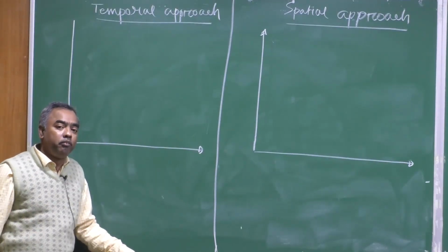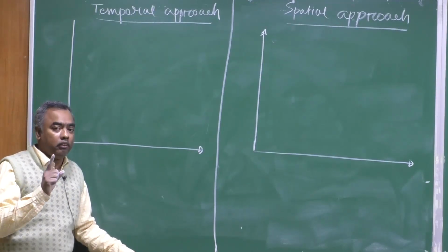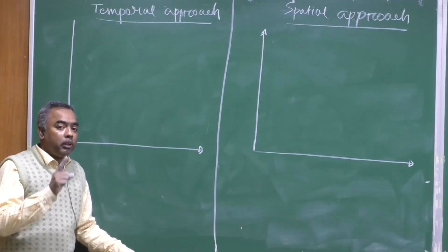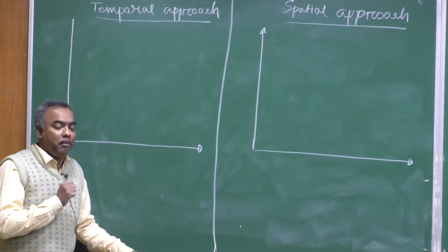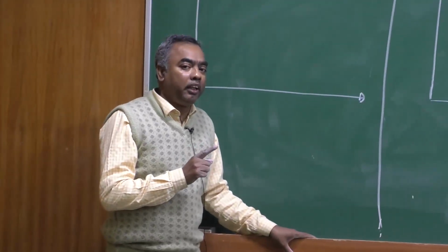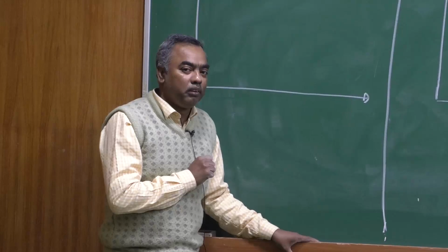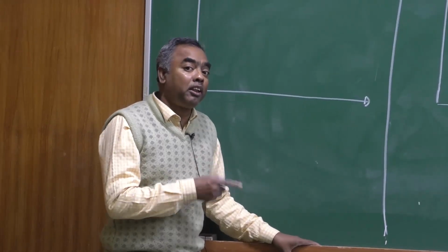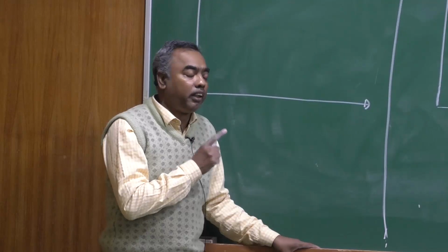And we have to look at what the most unstable eigenvalue is, meaning what the maximum value of C_i is. Because if C_i is maximum, the growth rate corresponding to that particular wave is maximum. So, we will be interested only in the wave which is growing fast. Okay.